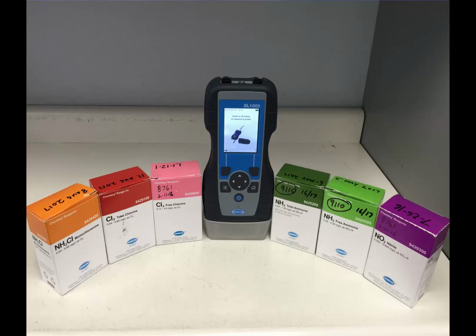So there's a lot we can do out in the field that we can get a more immediate result than that which we would take back to the lab. And then sometimes you get confirmation at the lab. Again, chlorine, though, the field test is going to be more accurate because the chlorine will dissipate in the sample by the time it gets to the lab. When we're doing chlorine tests, doing the field tests is very important to demonstrate what our actual chlorine residuals are out in the distribution system, which we will be talking about in a lot more detail in future modules.